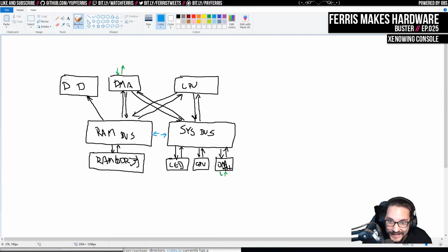In the middle of that, this display DMA might start reading, and then that needs to take priority, and that needs to read a bunch of stuff from RAM. And then when that's finished, the DMA can finish doing its job, and then the CPU can resume. So I need something that can handle multi-master like this really effectively.